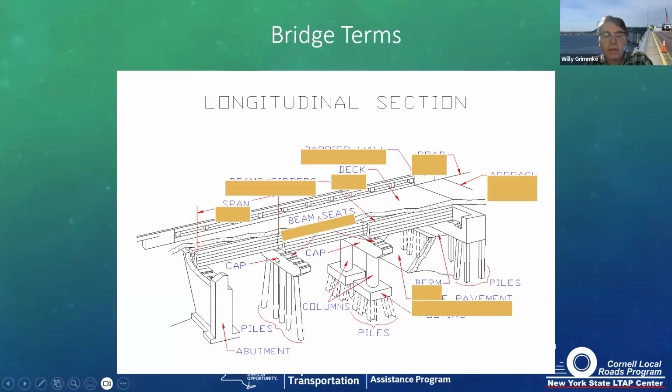We have a pile cap on this pier, and this particular pier is a pile bent pier where the piles are just driven into the ground and a cap is formed on top to support the superstructure, as opposed to the other one, which has pile caps at footing elevation level with columns extending above to the pier cap.